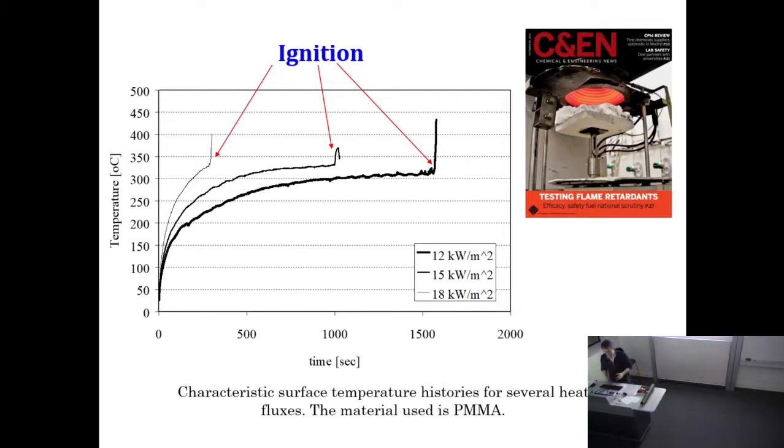Until now, I want to highlight this. It's something that we were writing about in the group recently. Flammability, as a scientific name, was first given to a mixture of gases. Flammability range, no? Upper flammability limit, lower flammability limit. In a gas, everything is simpler and nicer for science because it can actually put more depth into it. When you go to a solid, it complicates tremendously. It's still flammability, but it's just not about the ranges of mixture of the pyrolysis with the air. It's actually much more complex. It's also heat transfer. It's about flame spread. It's about many other different phenomena. Okay.